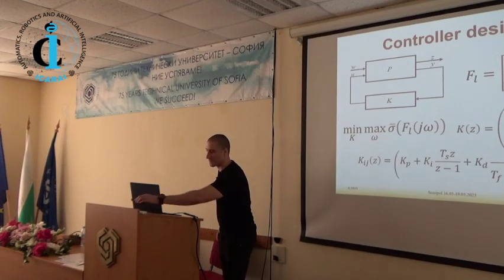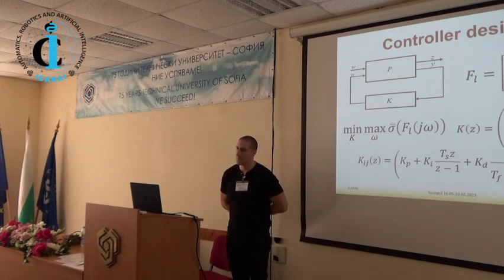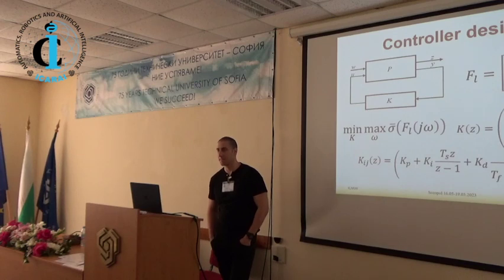So the approach of Apkarian and Noll is to first ensure the stability, and then they use steepest descent. This is not optimal for the general case, but in the case of designing such structured controllers, they show that the limitations are not so high in strength. So there is very high possibility that you obtain the optimal controller in this case. Even if not statistically, they prove that their controller is very close to the optimal.